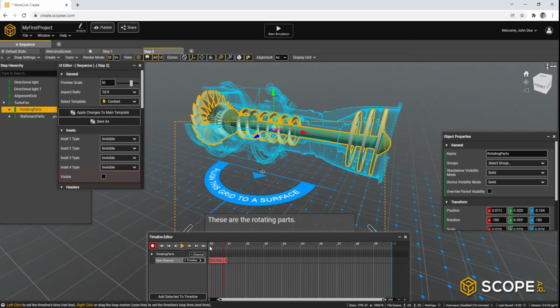In this case, you can see that the loop runs from 0 seconds to 10 seconds. You can shorten the timeline loop length by dragging the blue line to the left. So this is, for example, up to 4 seconds, or you can right-click the first second here to loop it to 1 second. So now when you play the animation, you can actually see we have a perfect loop created.